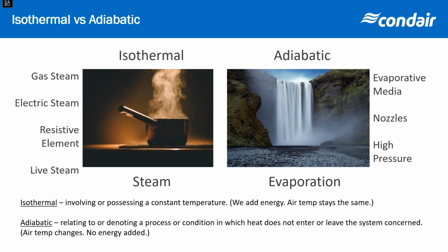More prevalent in the last 5 years has been the insurgence of adiabatic humidification, which includes a number of different technologies from evaporative to high pressure nozzles. Often it's for large projects, but also available for smaller projects. The reason it's become more prevalent in more recent years, I believe, is that it addresses maintenance and also addresses energy and can support some energy efficiency measures within your building.